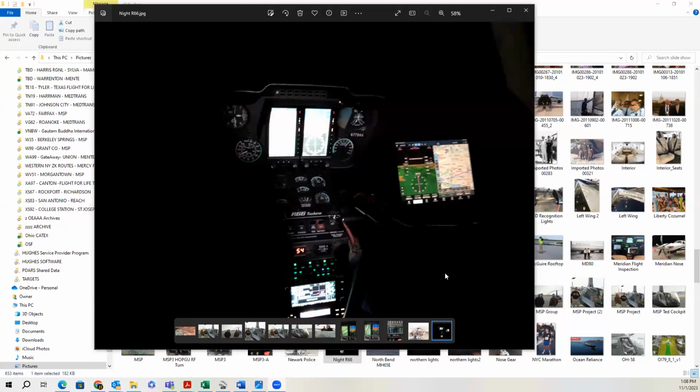Even on a clear night, when you're flying in mountainous terrain, you might as well be IMC in terms of spatial disorientation and an inability to see terrain. So you pretty much have to really be looking at what the grid MORAs are and then verifying your altitude to make sure you're above them in that sector, because obviously you're not going to see it.